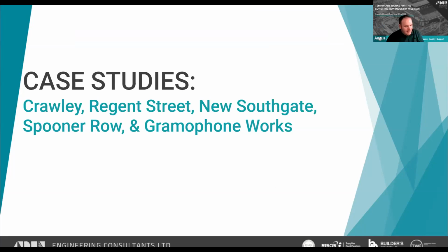All right. So today we're going to go through quite a few case studies, but we're not going in depth on the full project here. We're looking at aspects of what Josh has discussed, which is load history, load paths, those items really. I think a point to mention is you don't always have to maintain the load path of a structure, as Josh was touching on. You can change the load path, but you've got to be damn sure as to what you're doing. I think that's the key point to take away. And if you can keep your load path, then keep it.